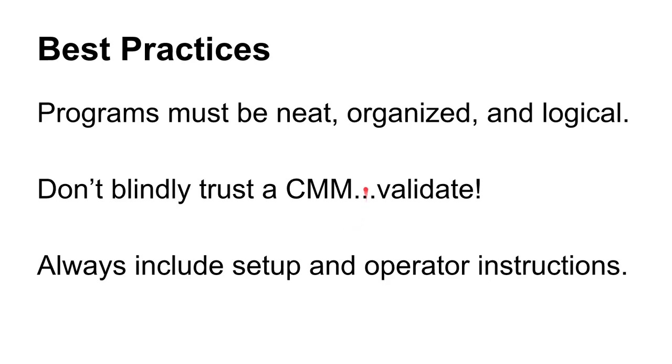Also, here's a news flash: a CMM will lie to you and give you bad information. Okay, I don't mean that they don't function well, but I mean that they function very precisely, and it will tell you exactly what you ask it. And so if you ask it a question, like you take 5 points on a surface and you say, is this surface flat?